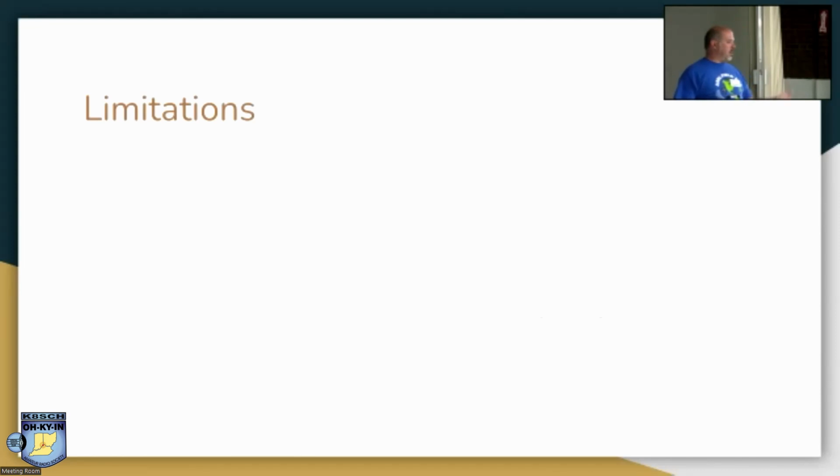Yes, so you could test amplifiers, as a device under test. So you set what your reference plane is, then you can hook up your RC filter, and a coil and capacitor type thing, parallel circuit, do those. Right, because all it's doing is, you think of this thing as a black box: whatever is going into that port and going out of that port is going into a black box. You may know what's inside that black box. It doesn't know. All it's saying is, I'm seeing at my end of my reference plane, at the end of that socket, I'm seeing these characteristics.